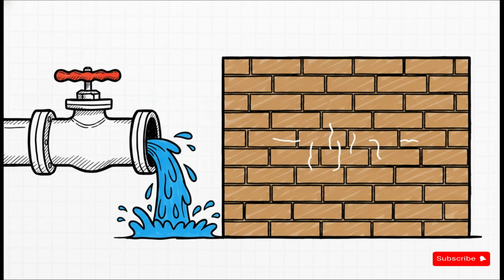Imagine you're trying to shut off a tiny water valve, right? But the water just keeps dripping, no matter how hard you turn the handle. That is exactly what happens when we shrink transistors too far. We encounter something called subthreshold leakage. This is when current just keeps flowing even when the gate voltage is completely below the required threshold to turn it on. And the kicker? It gets exponentially worse as that gate length gets shorter.